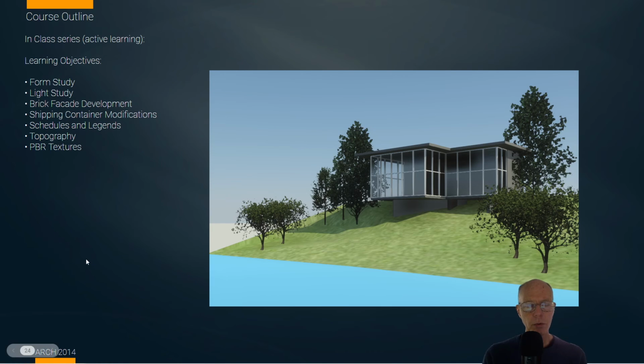They get a chance to, once again, I was talking about in topography, we actually create a freeform topography, so we invent a surface instead of importing one, and I show them how to do that, how to create the idea of a flat surface and water, and then we just put a building on top of that in order to create some kind of a setting.